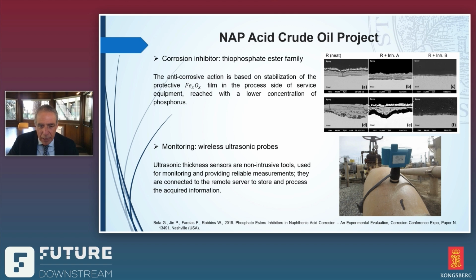As for the monitoring, we use ultrasonic probes that are adapted to be used in high temperature elements, because obviously the temperature is the most important factor that increases the corrosion mechanism. The higher the temperature, the higher is the corrosion mechanism.